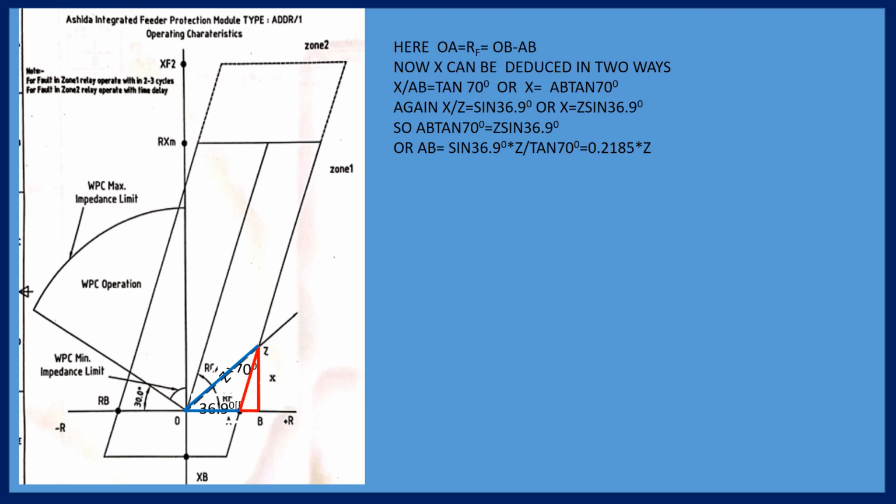But if you don't earth it, then it may be that the phase is 35 kV and your other end is 10 kV. That is also a 25 kV difference. The potential difference is 25 kV. So we are keeping one end at 0 in the potential transformer, in the current transformer, and in the auxiliary transformer.